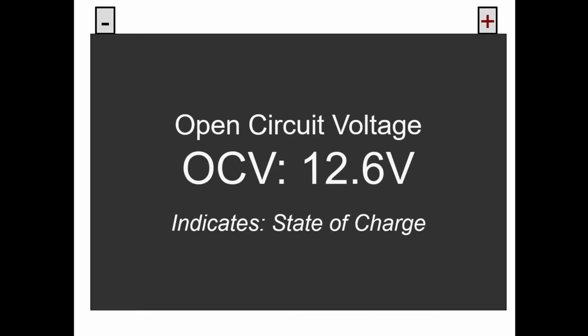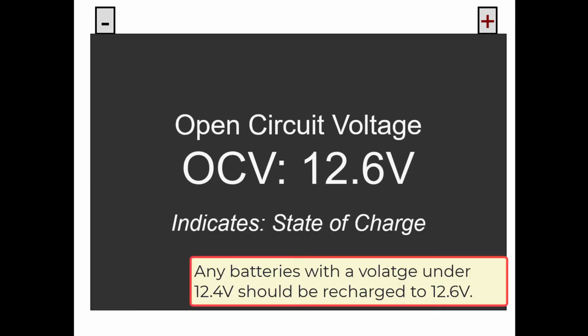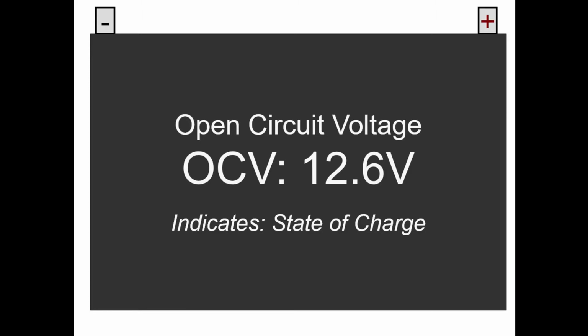So this is a good indicator when you're first starting out, especially if you have a vehicle that's been just taken into your bay or into your shop. You can quickly check the voltage, and if the voltage is low, you might want to put a charger on it before you do any other types of diagnostic, especially when it comes to looking at your starter or looking at your alternator. It's always good to work with a battery that's fully charged.